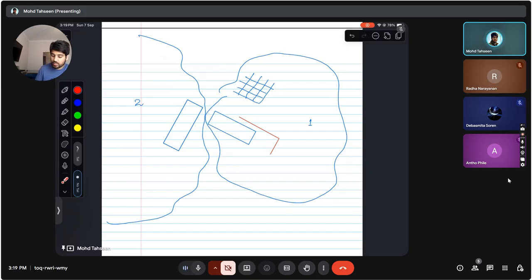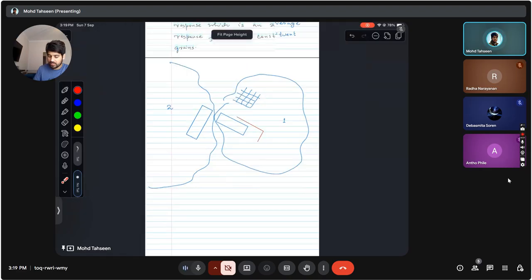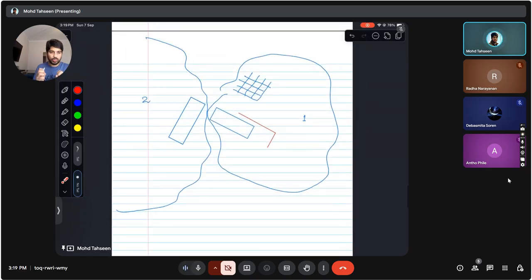Now in such a case, if I am to measure the properties, what do I expect? I expect that this behavior will be exactly cancelled out by this behavior. Let's say these grains are very small, and so it doesn't recognize whether the load is being applied on one grain or the second grain. It just applies a load on average on the material. But the internal structuring of the material is such that these two effects can cancel each other out.